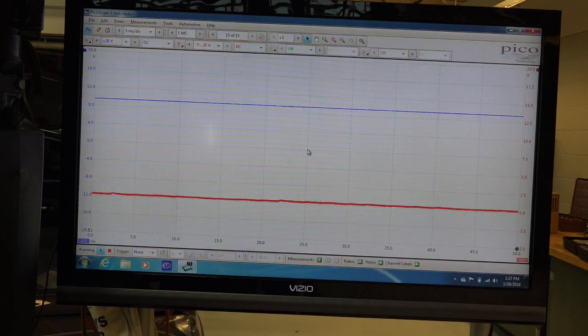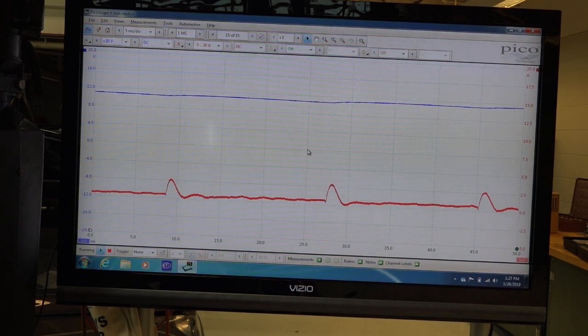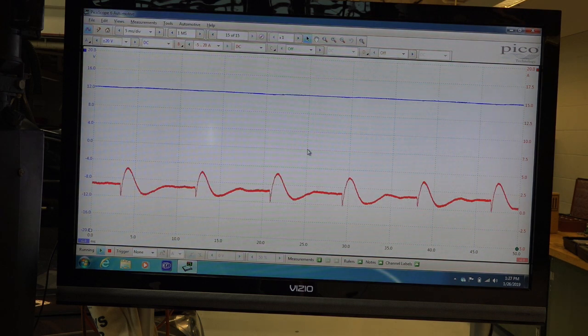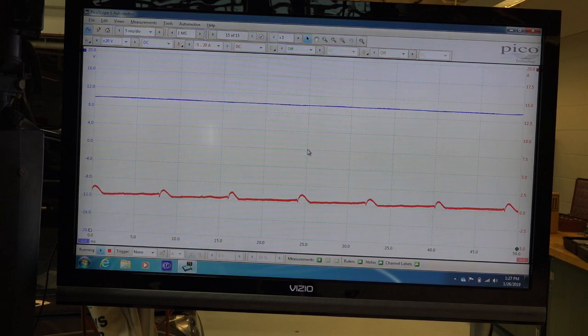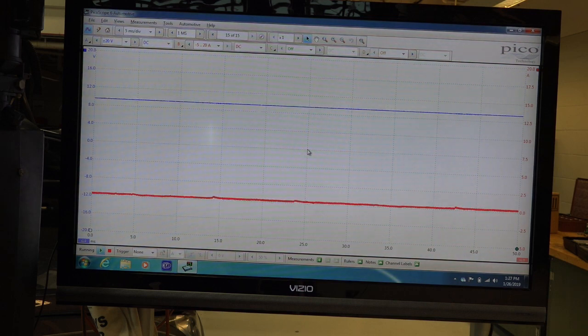Now, I can open the wire, the speed control, either at the blower motor here or back at the programmer. Or what I'm going to try, it's a little easier, I'm going to unplug the fuse that is the battery hot on that programmer. And hopefully we'll find something this way.